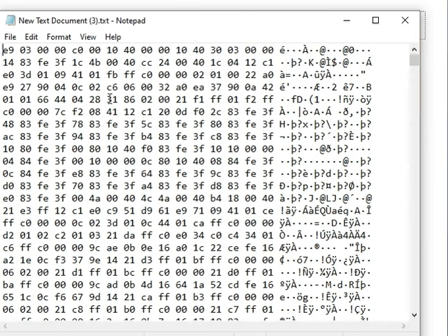Now, the simplest thing it does is, as soon as you turn on your ESP8266, it is going to blink, saying that the hardware unit, the ESP8266 unit, is in a working state. Just to show whether the ESP8266 module is in working state, you will get a green LED blinking. So when you put this piece of code onto the controller, the LED will blink, indicating that all the hardware present in that ESP8266 is working fine.